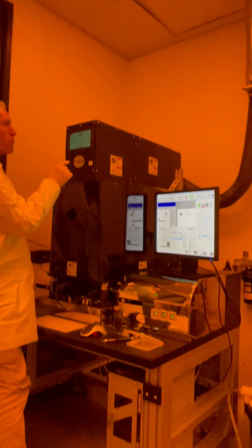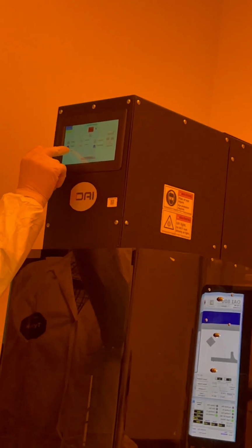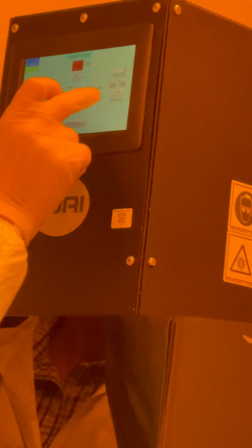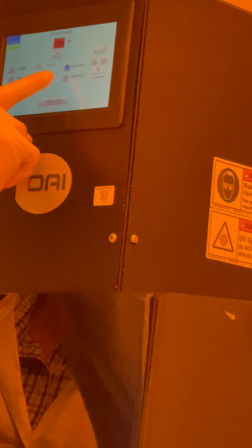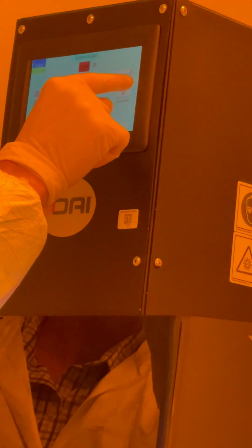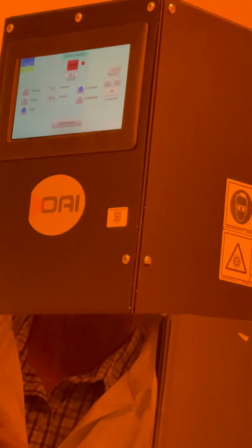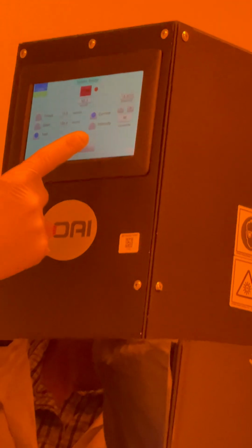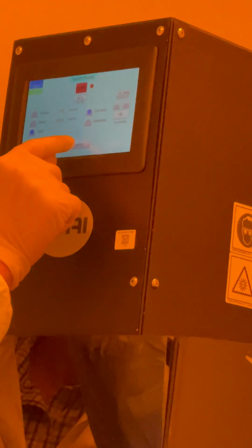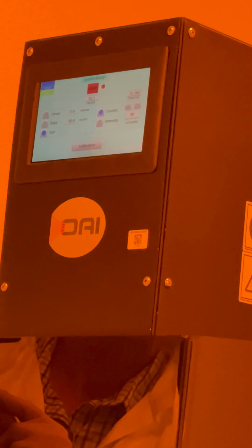So to do it, you put it in test mode. And instead of intensity mode, you put it into current mode, so it's only driving a constant current. And then we usually like to calibrate it at like 90%. So we say 90%, we turn it on, we wait till it stabilizes, and then we go to calibration.